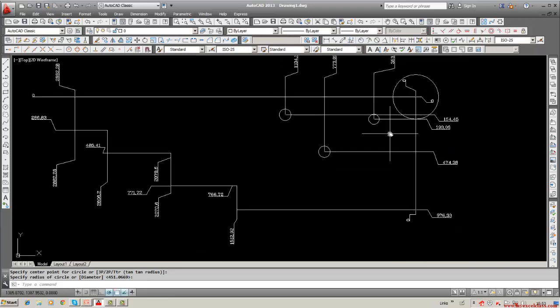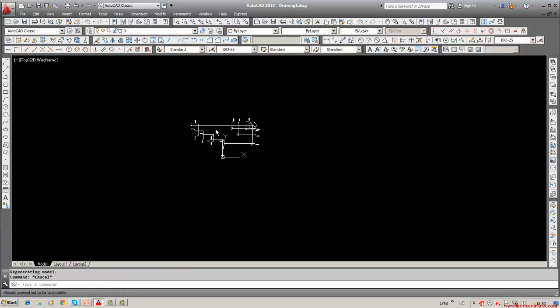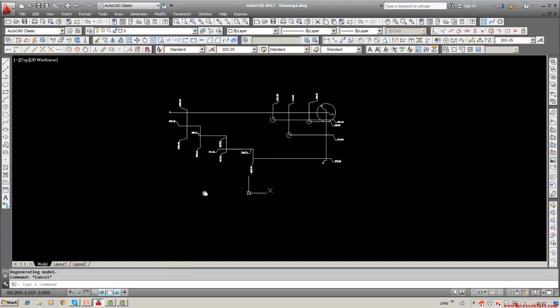Okay, and then you shift the component to zero position. For that you have to draw another circle at 0 position so that you can shift the component exactly to 0, 0. Select circle to be drawn. Select 0, 0, absolute 0, 0. You have drawn a circle and shift the component.